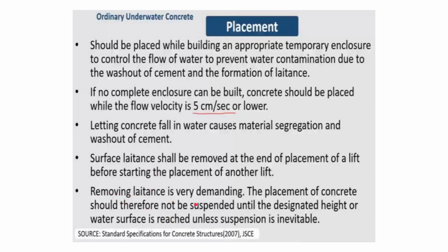Okay, removing laitance is very demanding. The placement of concrete should therefore not be suspended until the designated height or water surface is reached, unless suspension is inevitable. So here, because there is no issue of heat liberation, heat of hydration, it's better, as much as possible, to cast the concrete in fewer lifts. Okay, the fewer the lifts required, the better it is. Okay, because otherwise you have to take care of the laitance and all the segregation criteria.